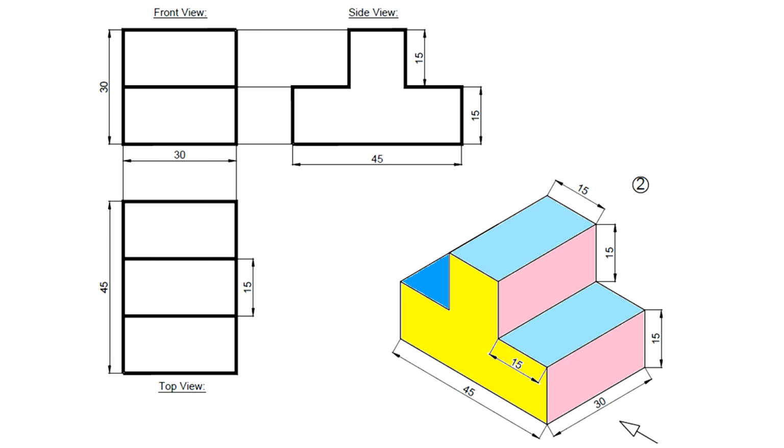So that means when you draw the front view like this, the xy axis or xy reference line is here. When you draw the top view, the xy reference line will also be here. So these two will be coming below the xy reference line. So these three surfaces will be drawn below xy, and this is the front view, and this is the top view, and then the side view. This becomes the side view, the yellow color one, and the yellow color surface will be drawn here, and this is the side view. So the front view, top view, and side view are drawn here, and this is the pictorial. So based on the arrow mark, the views will change.